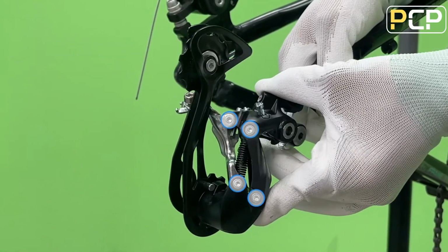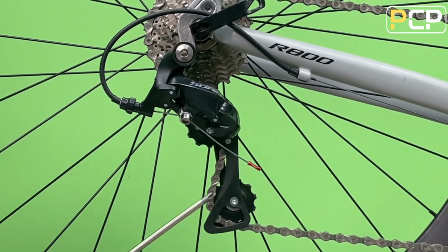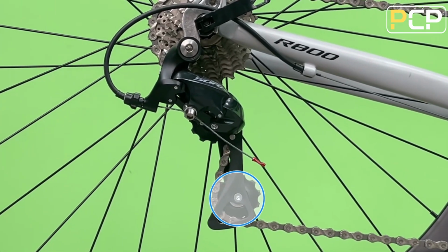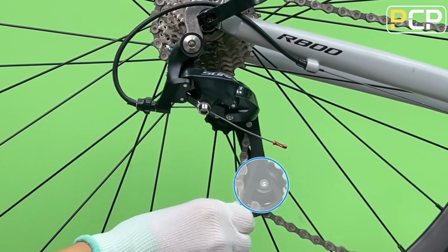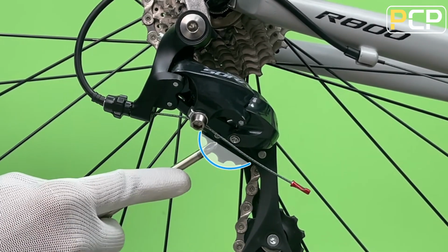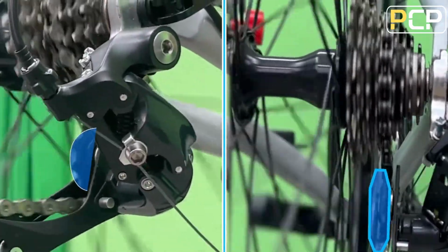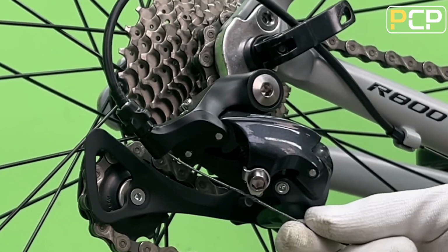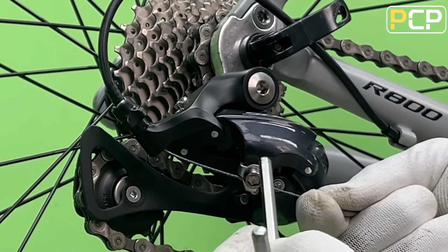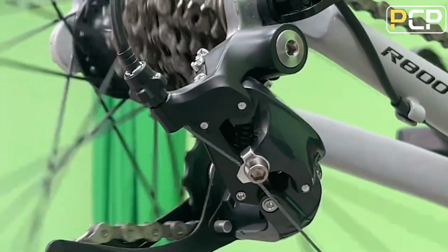The top normal rear derailleurs return the chain to the smallest sprocket on the cassette when no cable tension is applied. This is the regular pattern used on most Shimano mountain, all Shimano road, and all SRAM and Campagnolo derailleurs. In this condition, spring pressure takes care of the easier change to smaller sprockets. In road racing, the swiftest gear changes are required on the sprints to the finish line, hence high normal types, which allow a quick change to a higher gear, remain the preference.